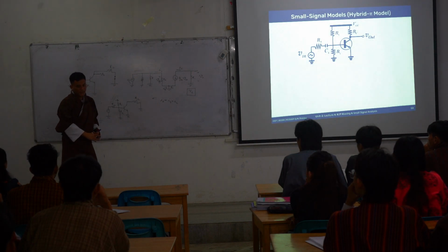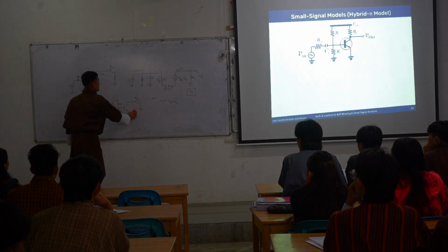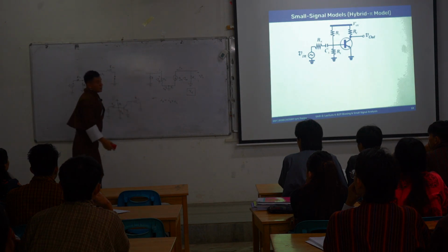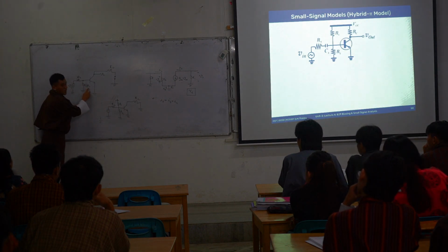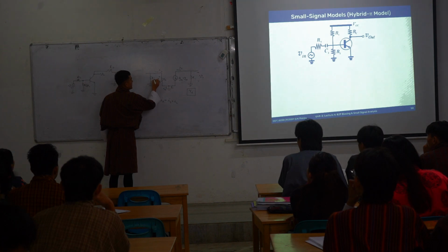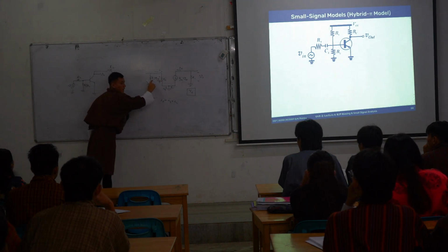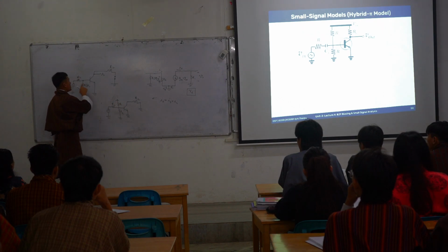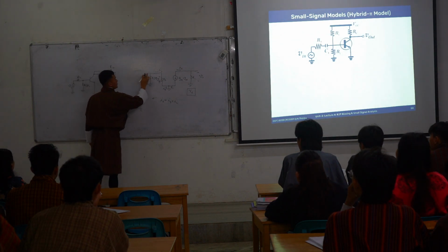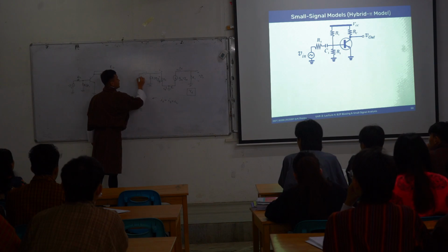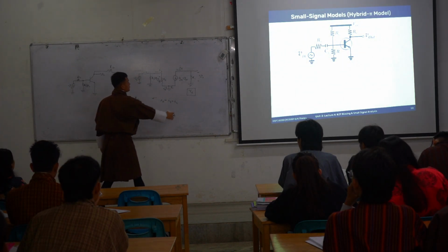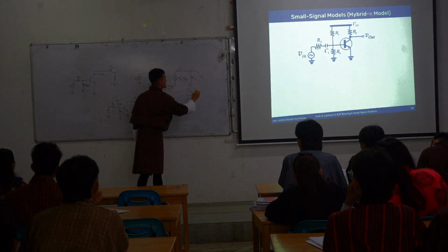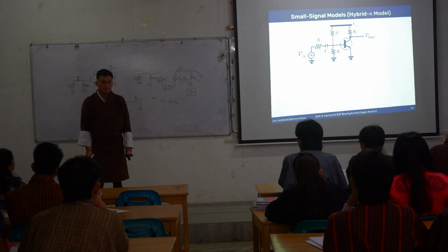Now in order to modify here, it's very simple. This is the input side. On the input side, you have R1 parallel to R2, and this R1 and R2 parallel combination is again parallel to your RS. You have now RS, then you have the actual AC source VS. This would be the changes there. However, your output side will remain the same. This is just your RC.